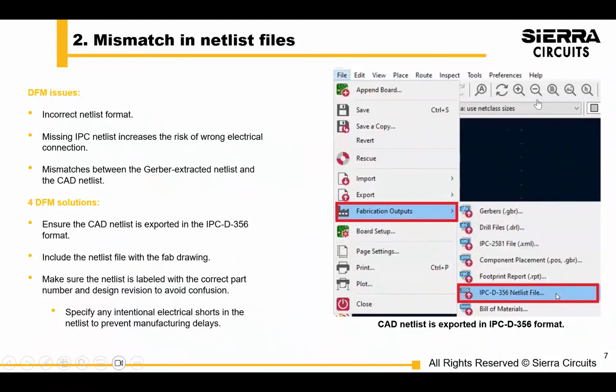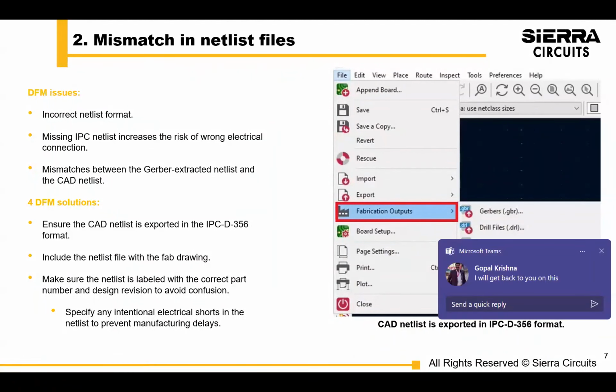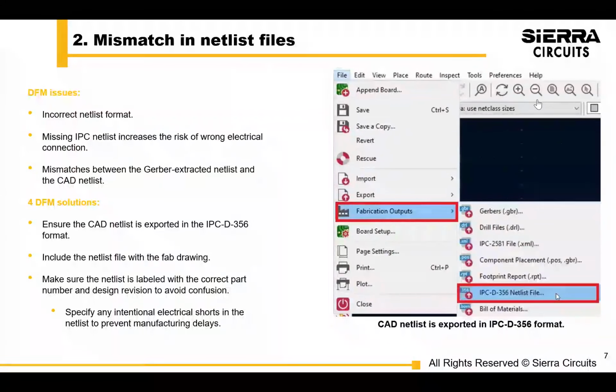Netlist is also a big deal. When we get your boards to the finished state and we're doing a flying probe electrical test, did we create our own netlist off of your Gerber data, or did it come built into the ODB++ or IPC file? If it comes in the IPC file, much better, because we're then comparing to your schematic.